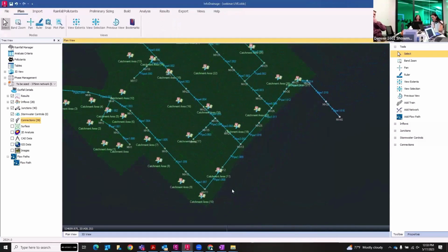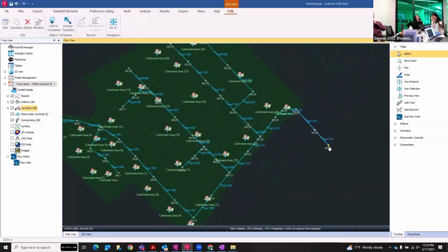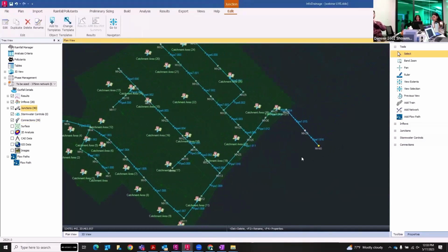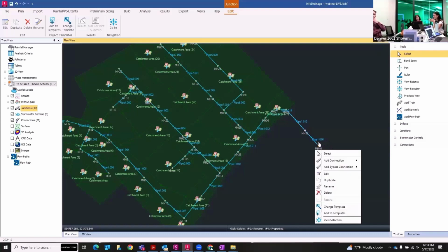Another change that I'll make to this demonstration is I'll add an element that doesn't exist right now in Civil 3D. What I mean by that is, in Civil 3D pipe networks, you basically have structures and pipes, and those are the two elements that make up a Civil 3D pipe network. But obviously in your drainage design and the modeling aspect of it, there's a lot more components than that. You could have open channels and, of course, your stormwater controls. Those don't actually exist in Civil 3D right now.